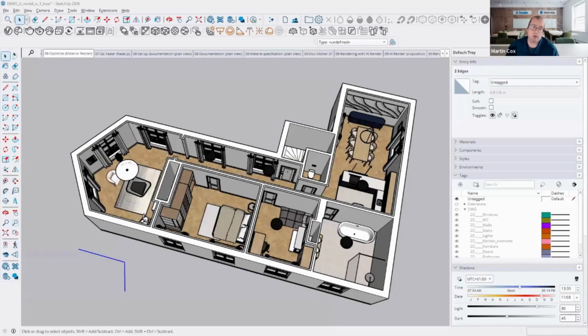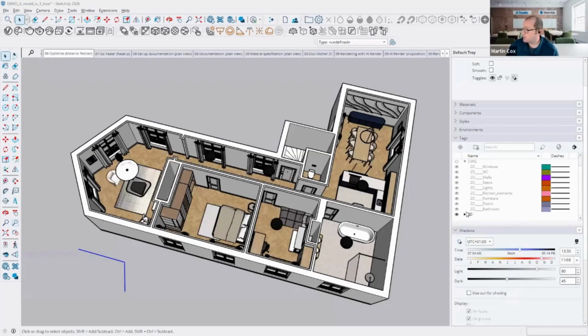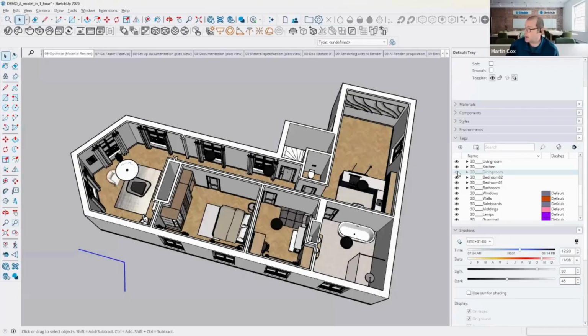It really is, yeah. So it is around updating those scenes, turning things on and off within tags. Within 3D here, everything's nicely managed in tags. You can even have tag folders, which are brilliant because then you can turn multiple things off. If I turn off what's in the dining room there, I update my scene. I can either right click on it and choose update, or I can do this from the scene manager, and that will update my scene with the furniture there.